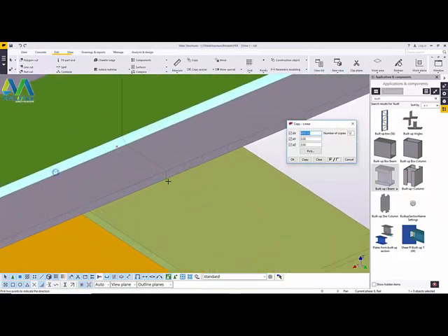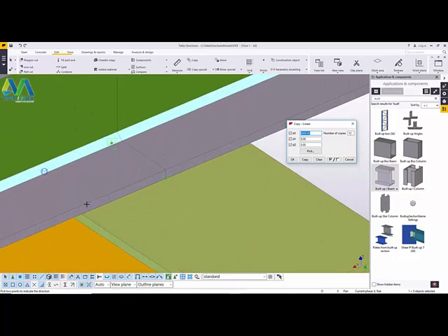Now I want to populate this point in that direction and in this direction. First of all, before doing that, check the positions and the direction of your x-axis. The x-axis is pointing in this direction, so we want to offset this point by 100, or by 100 is okay. 100 is much. We'll give it 75 and reduce this number to 1 and click copy.